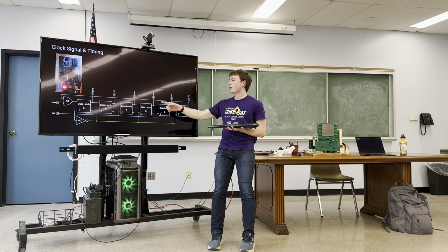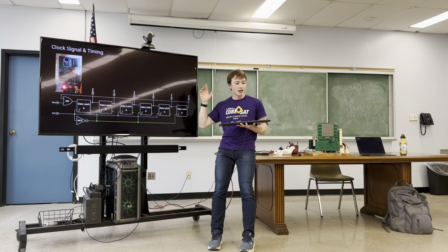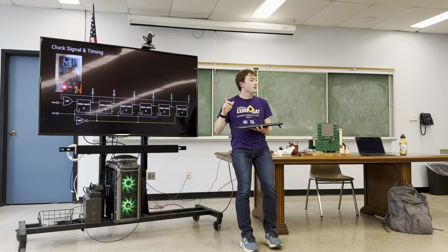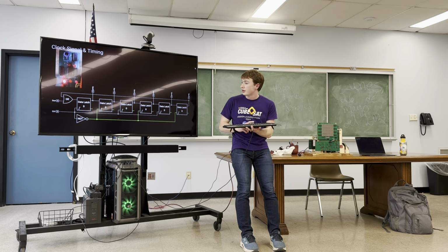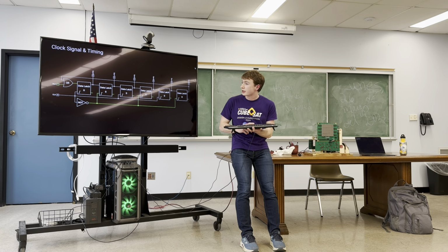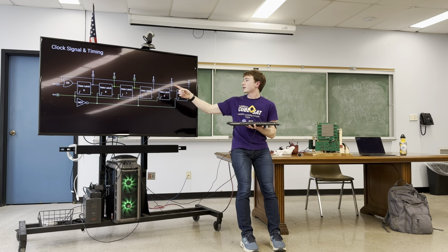So if there are any ones, logic high values, in these, they'll get flushed out. The capacitor gives it enough clock cycles for them to be 0, and then it'll start the sequence.